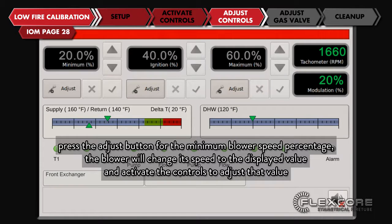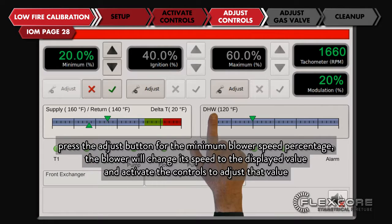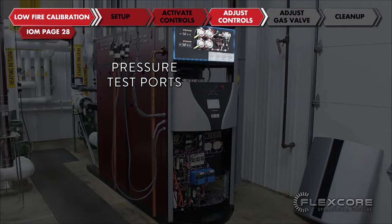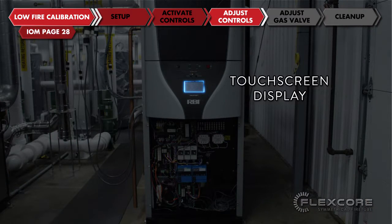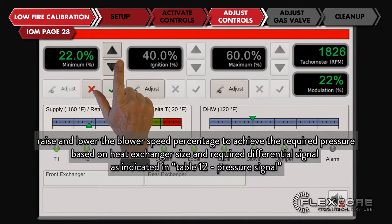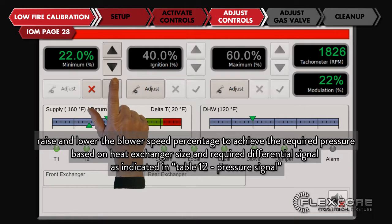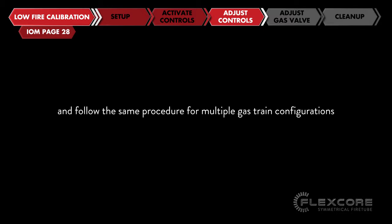Press the adjust button for minimum blower speed percentage. The blower will change its speed to the displayed value and activate the controls to adjust that value. Read the manometer attached to the differential pressure test port and note the offset. Raise and lower the blower speed percentage to achieve the required pressure based on heat exchanger size and required differential signal as indicated in Table 12, Pressure Signal. And follow the same procedure for multiple gas train configurations.